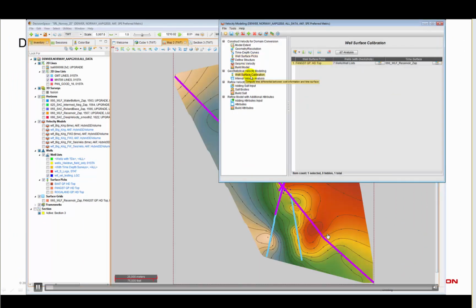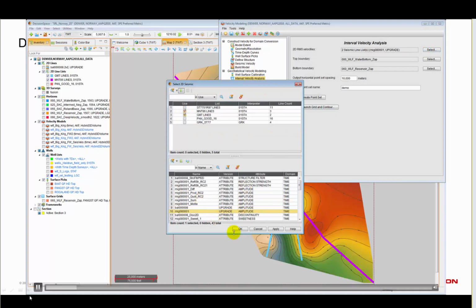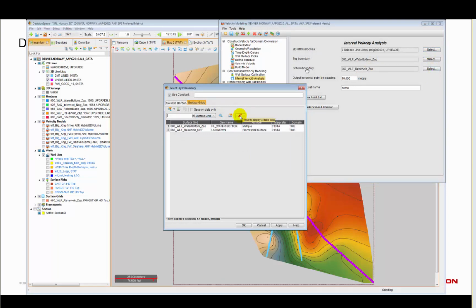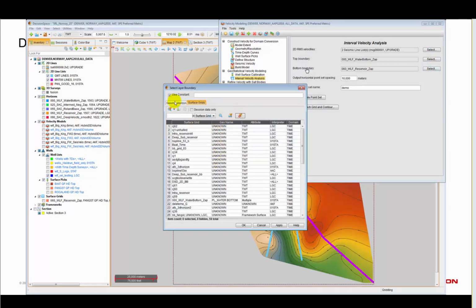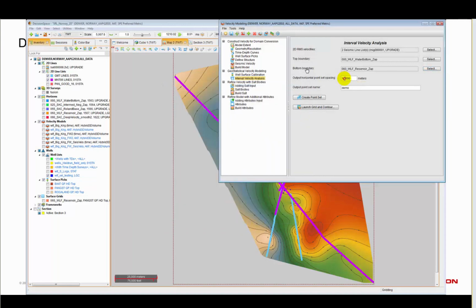So I got my giant 2D prospects here, and I can do my check shot analysis. I showed that before. And then we go into the 2D velocity. So again, I can select multiple 2D line lists. I can select hundreds or thousands of 2D lines of seismic velocities to analyze. And then I select what layer I want to analyze. Typically you'll go from top down, but I could analyze, say, my chalk zone in this particular example, or I can analyze my shale zone,